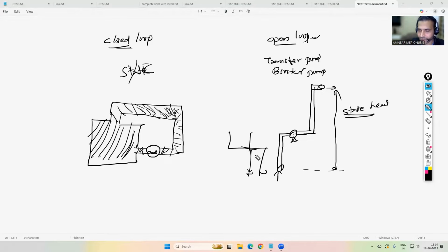In the water supply system, we have discussed that in a very detailed manner, or that transfer pump calculation video I have uploaded on our YouTube channel as well. You can watch that. Correct. So only by gravity, sometimes we will not be receiving that pressure. Then we have to go for a booster system. Correct. If by gravity we are not getting it, then we will be going for the booster system.